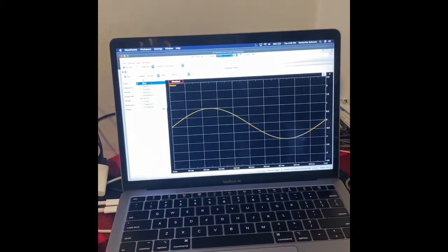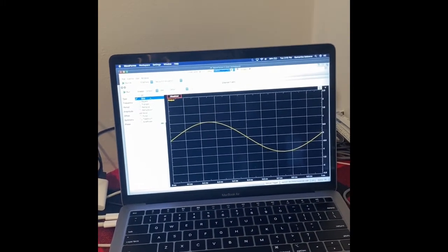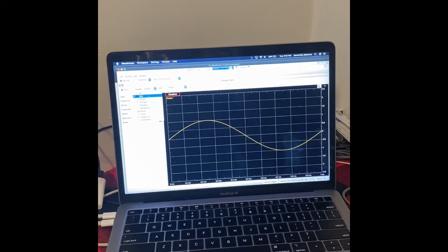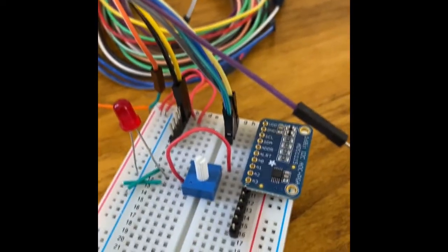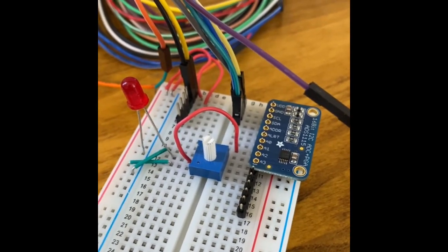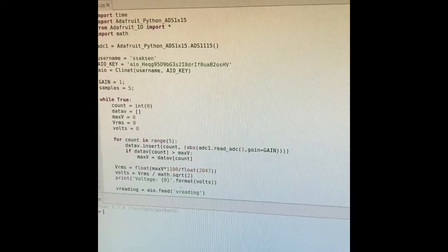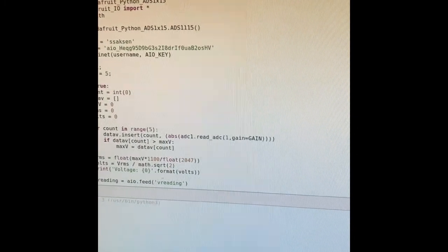Using the accompanying software for the Analog Discovery 2, any AC voltage waveform can be simulated. Then using the AD2's oscilloscope, I can measure the input voltage at the A1 pin of the ADC chip and use that value to determine within my Raspberry Pi code the conversion between what is being read at the A1 port and what is being outputted.